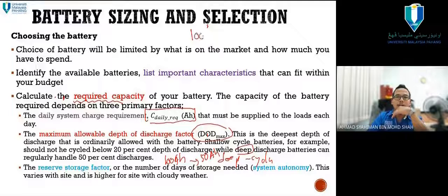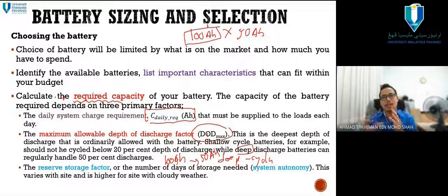Okay, 100 AH on the outside, on the box. It's actually not there. If you think you get 100 AH, that is the big mistake. You need to think it's actually half of that. It may be able to push a bit more, but you must have that kind of mindset. Okay, a 100 AH battery is actually 50 AH.